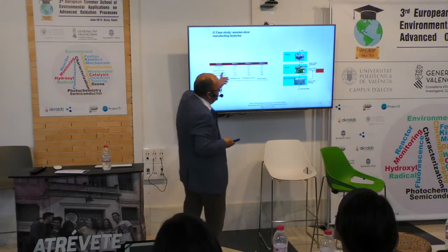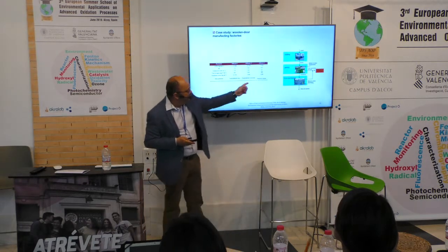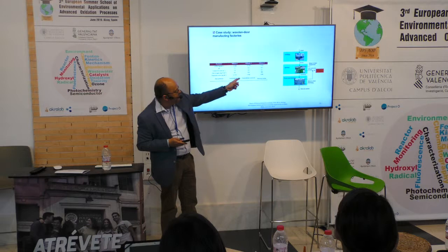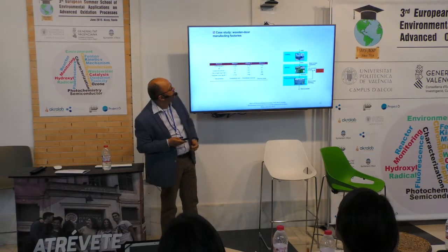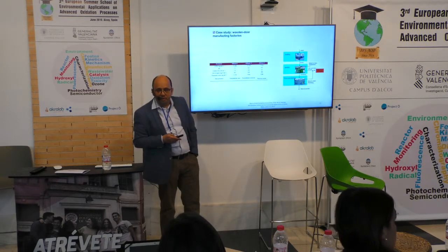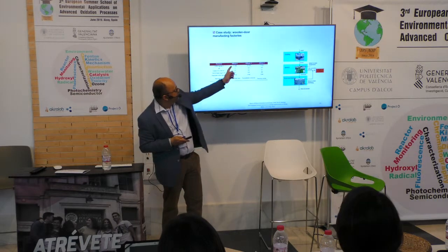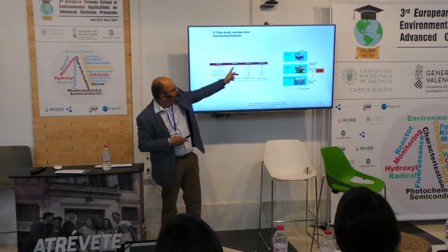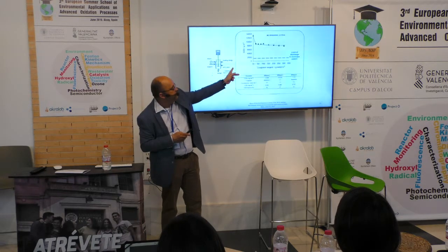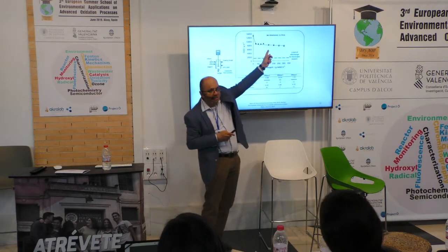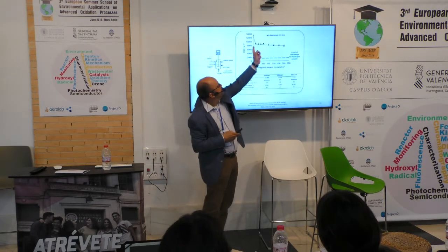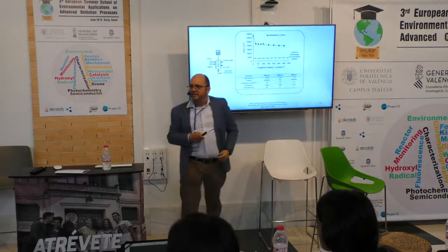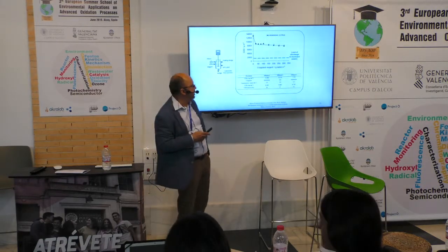These are results that we made for a group of companies regarding the wooden door manufacturing process. And in this case, you look that you have water with a quality of around between 10,000 and 15,000 ppm of COD. After the chemical coagulation, you can decrease the COD down to 8,000.